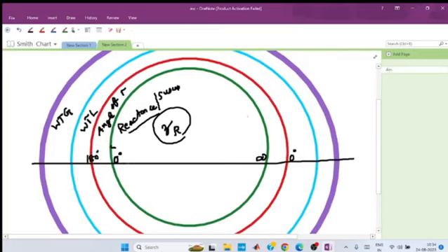180 degrees, right? So 0, 10, 20, 30, likewise it will vary 30, 40, 50, and the values keep varying up to some infinity. Similarly 0 here, then minus 10, minus 20, and similarly here minus 170 is there. So this is the typical scale used for finding the angle of the reflection coefficient, right?